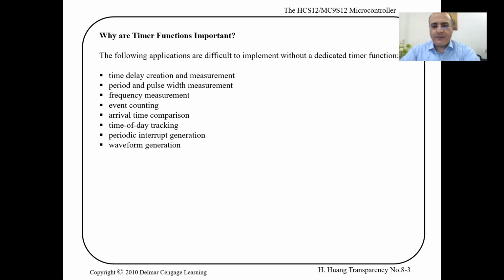If you remember, in the interrupt chapter, we covered an interrupt called real-time interrupt, and we were able to generate periodic interrupts that we could use to generate something every amount of time, as a background for a hardware-based delay, or to periodically call a function or a task or whatever.